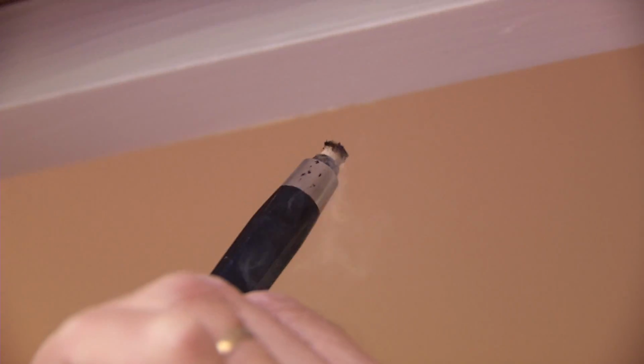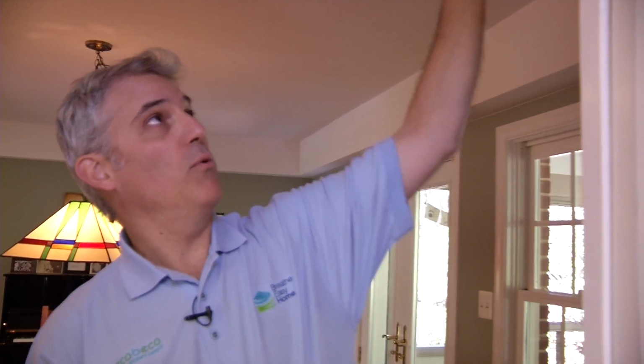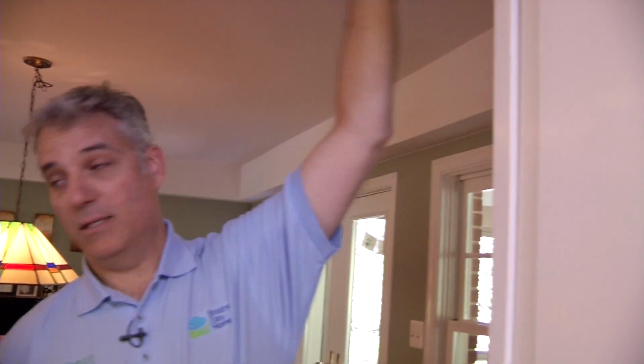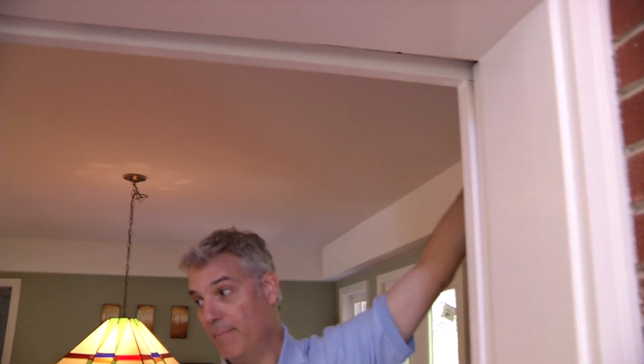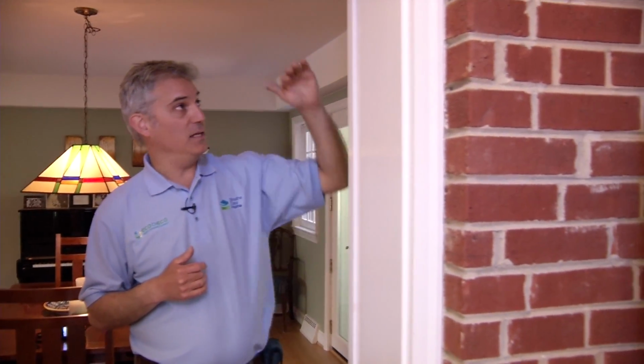It's so hard because they have to be framed in such a large area, but they weren't sealed around it. So what we're going to do is cut open this area here, try and get above them. It may require some work on the side. But the idea is just to seal all the framing around the pocket door to make sure that it's not leaking air into the house.